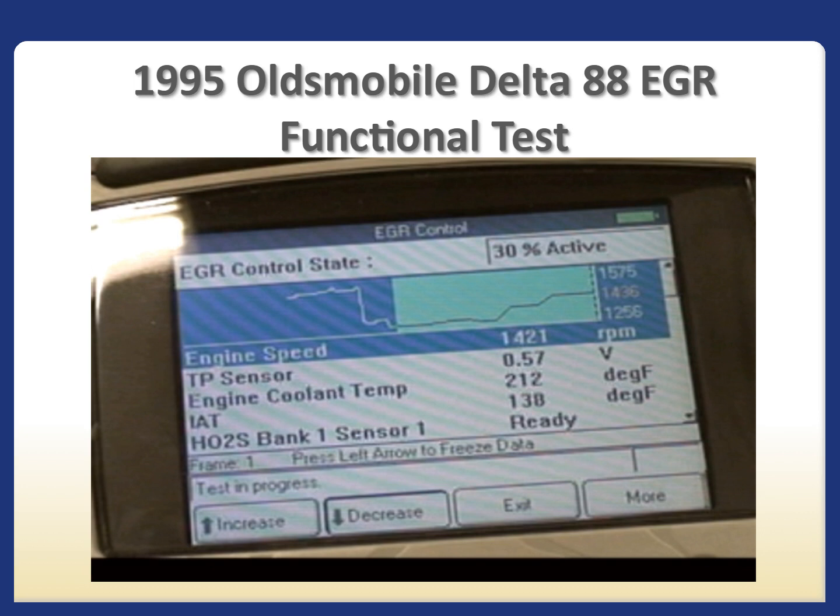Carefully listen to the vehicle's engine RPM drop when the inspector cycles the EGR valve from 0 to 100%. When the EGR valve is opened to approximately 80%, the engine begins to run rough and the RPM starts to drop. As the EGR valve opening is increased from 80% to approximately 90%, the engine starts to stumble and die. The RPM drops, indicating that the EGR valve is open and the passageways are clear.